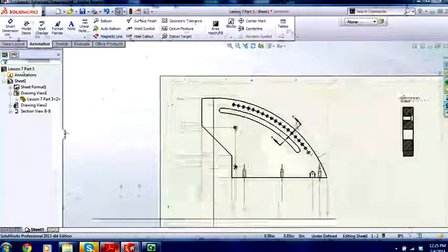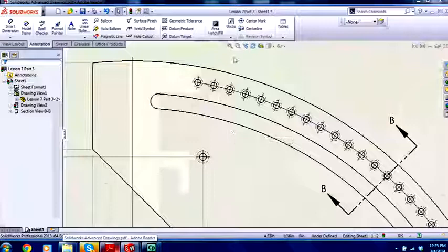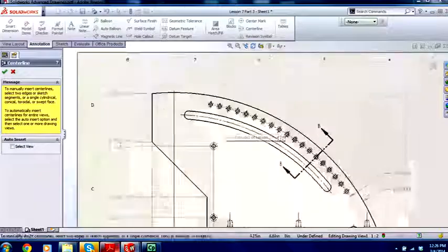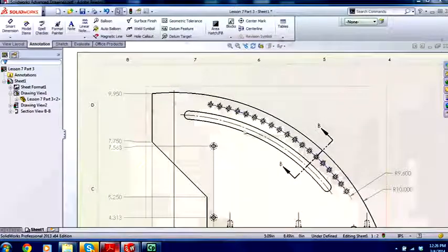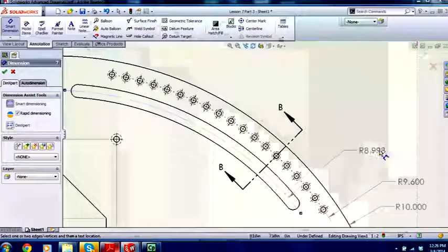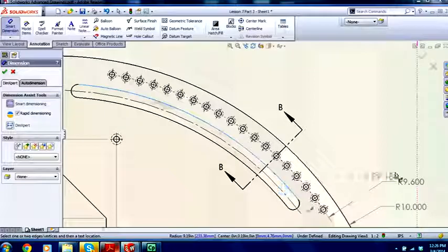So let's just do it the way they drew it, this way for a reason. Pretty tricky. Center line. Is there a? Oh, look at that, lovely, nice little center line there from the slot, one edge to the other edge. I'm pretty sure they're dimensioning that edge, 9.188.